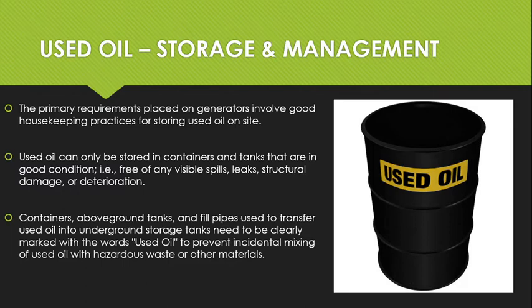And the same goes for oily absorbents. Let's say I'm telling you, hey, we're going to send those oily absorbents to Midstate or Valacor. It's going for recycle, which means it has to be managed under used oil rules. However, if I say that hydraulic oil and absorbents are going to the landfill, like Turkey Creek or Testman or Waste Management, then we don't have to have it in secondary containment. We don't have to label it as used oil. It's actually easier to send this stuff to the landfill than it is to send it for recycle, which is strange to me. I think you'd want to encourage people to recycle it, but those are the rules. So just pay attention to where I tell you it's getting sent, and if I'm asking for certain things, management-wise, this is why.